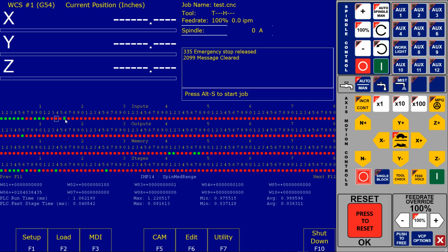And of course, I didn't flip the switch, so the input is in fact in an open state, and you can see that my output is still on, because my output is just looking to make sure that this condition is true. And as long as this input is green, then this output will turn on. And so now when I close the switch, even though it's closed, my output turned off, where before my output would turn on when it's closed. Now my output is turning on when that input is open.